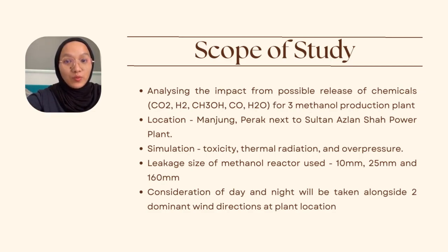So the simulation will include all possible scenarios in terms of toxicity, thermal radiation, and overpressure. And the leakage of the reactor that are used are 10 mm, 25 mm, and 160 mm, with consideration of day and night, with wind blowing from north and west.